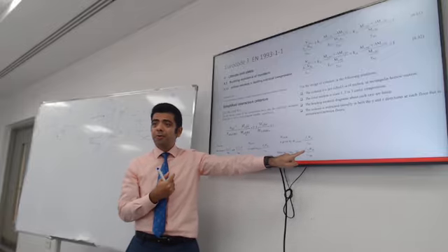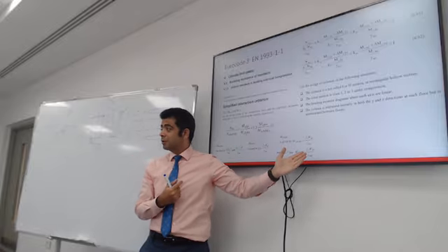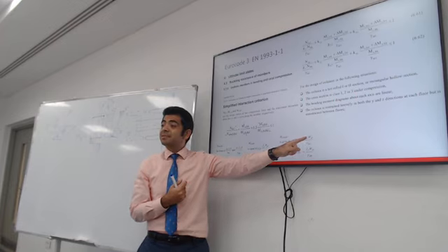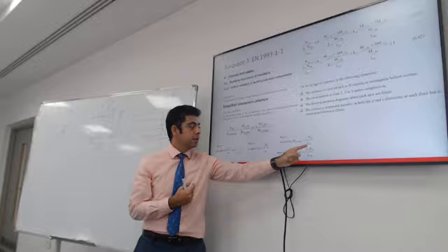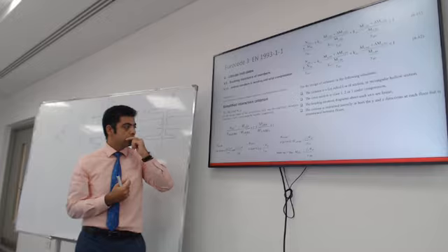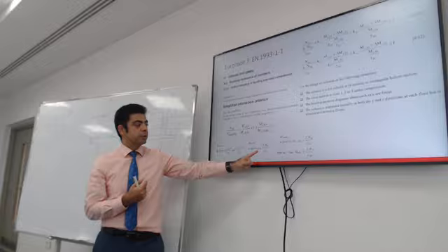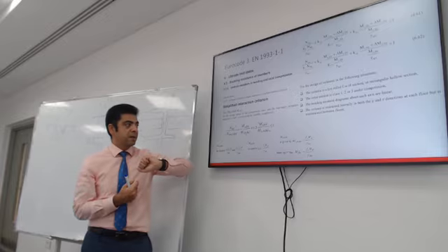You should go refer to it to get these factors. What's the partial safety factor? What's the plastic section modulus? And F yield, how do we figure it out? And we will need the reduction factor for lateral torsion buckling in the Y capacity.